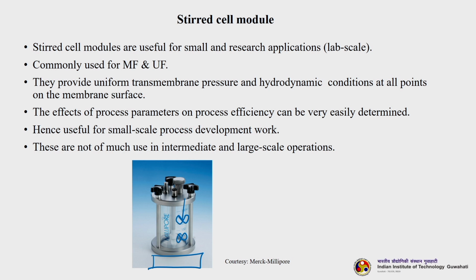So, the material inside the module will be stirred. These are useful for small research applications, usually lab scale. There is no commercial application of this in large scale operations. It is commonly used to characterize microfiltration and ultrafiltration membranes. The beauty of this module is that it provides uniform transmembrane pressure and hydrodynamic conditions at all points of the membrane surface, because it is a dead end filtration and batch type.